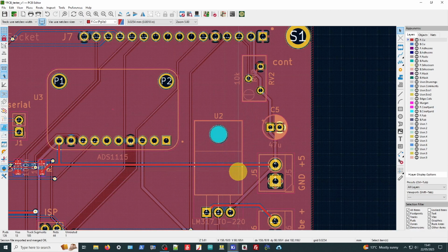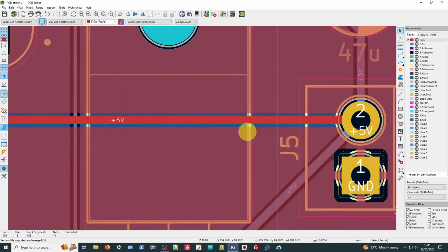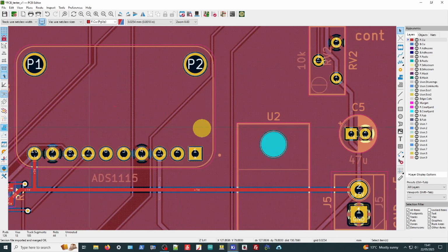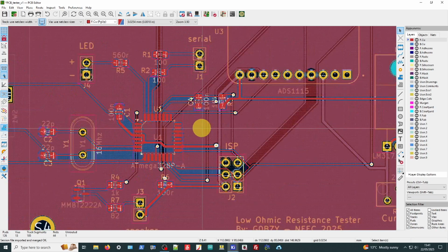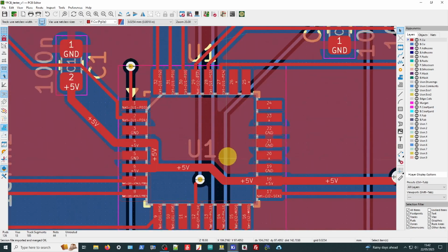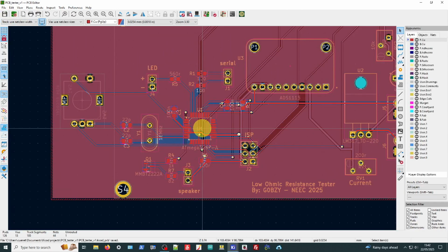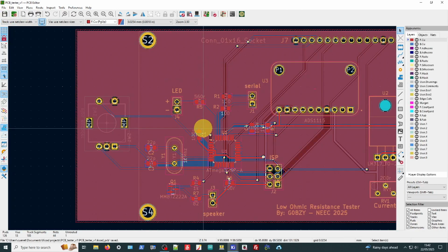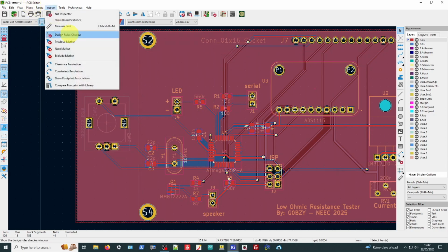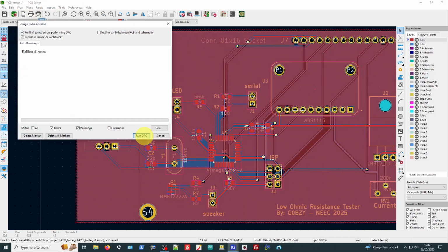Now we actually have insulation between the positive rail there and the actual copper fill, and it's gone round and basically it's done everything. That's mostly done. I'll click save. So we're getting pretty close here, but what we'll have to do of course is run the DRC and just see what state we're in. You can guarantee there will be errors. Let's have a look and run the DRC. How many errors? That's the question.